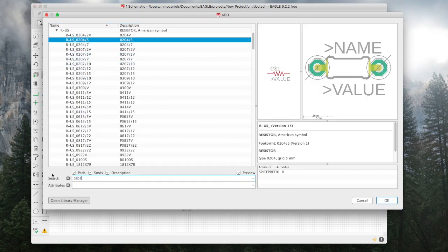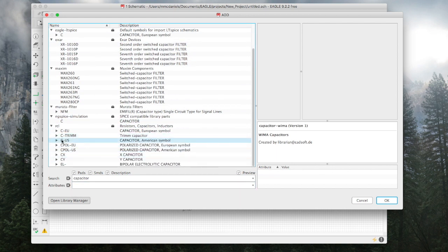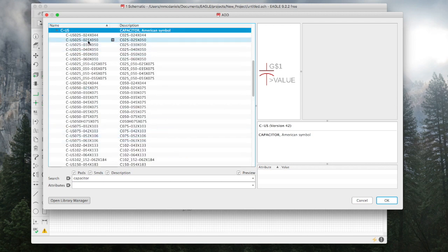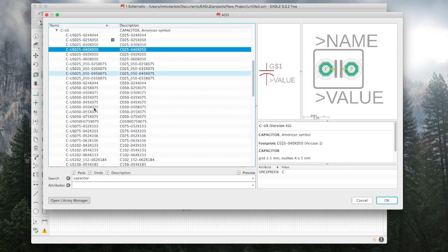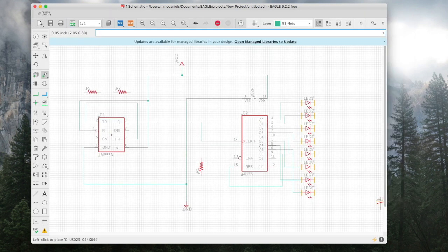I could have used a TTL decade counter, but those are restricted to about 6 volts maximum, and I would have had a little bit more trouble with the battery connectors, etc. I would have had to have used 3 or 4 1.5 volt AAs or AAAs. 9 volts are just so convenient. So I decided to use the CMOS decade counter on the right, which is the 4017.